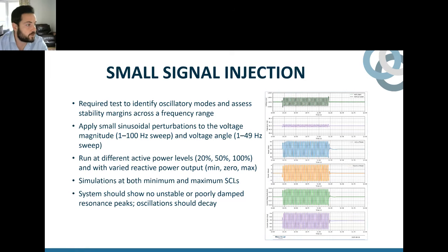The frequency trace shows a corresponding 10 hertz ripple around the nominal 50 hertz, indicating that the system is responding to the injected signal. But the key takeaway here is that for this particular 10 hertz frequency, the plant interacts strongly with the network, as you can see, from around 10.25 seconds to 11.25.